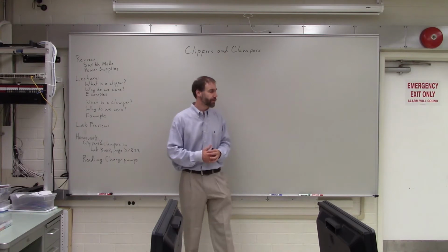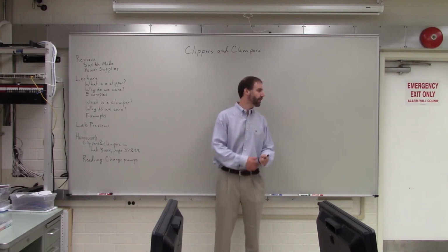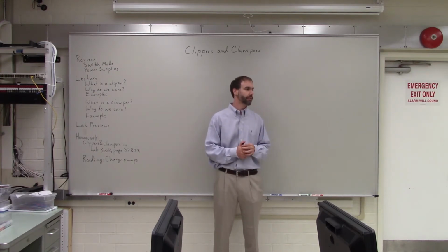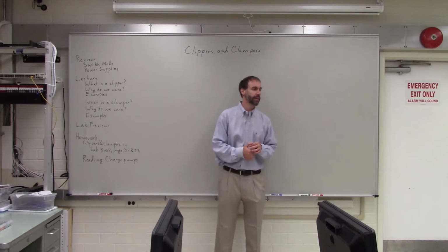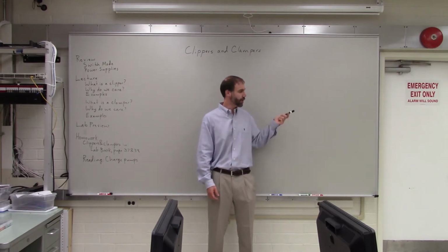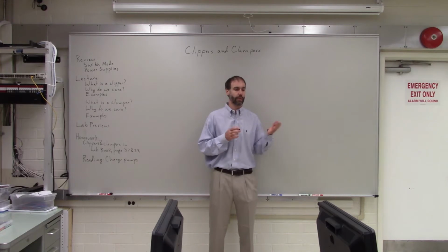Okay. So what was an advantage of having very, very high frequency switching? Yeah. Efficiency. Yeah, efficiency, exactly. When it was switching on and off like that, it was much easier to filter. So you could use smaller components to do the filtering, and that filtering was more efficient.